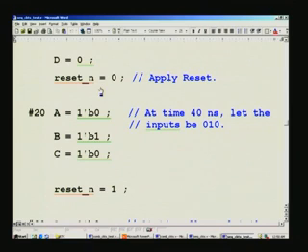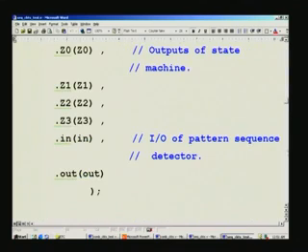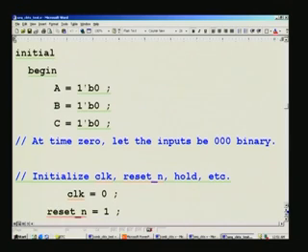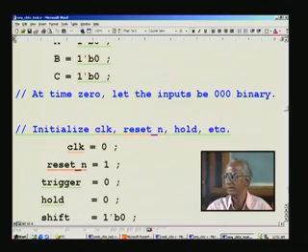And similarly, now only we are applying the reset. This is the power on reset we said, or system reset. So, earlier had you noticed that one, it would have been 1, right, it is 1 here. So, to start with it was 0 nanosecond, let us not reset immediately, we will give some time lag and then reset the system, right. 1 will not reset because of the negation here. So, it is active low, that is what we have already seen, asynchronous active low.